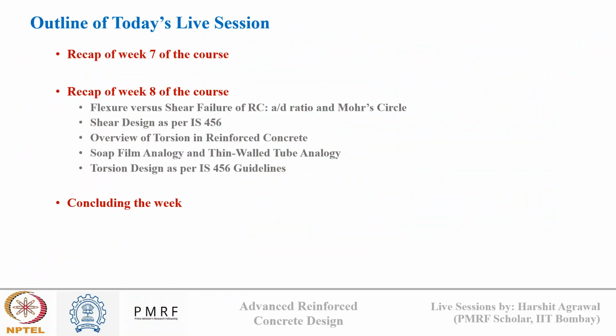In today's session, we'll continue our discussion first on what we left in the last session, that was based on understanding the flexure versus shear failure of reinforced concrete. In this, we will discuss understanding the concept of a by d ratio and Mohr circle. Then we'll see shear reinforcement design of an RC member based on IS 456 guidelines.